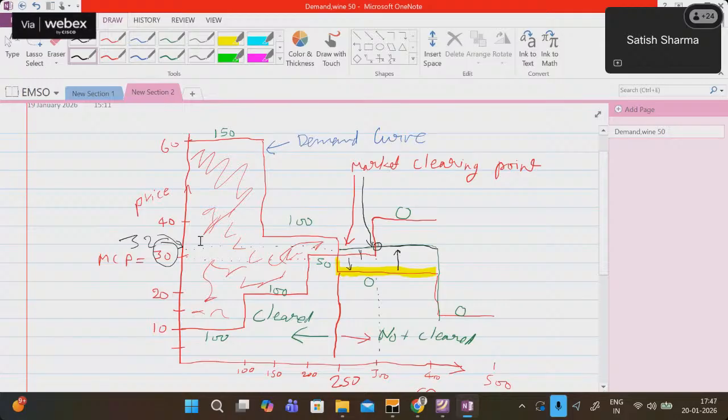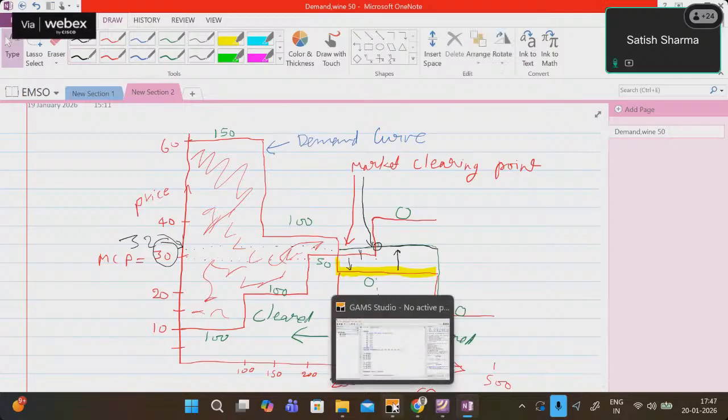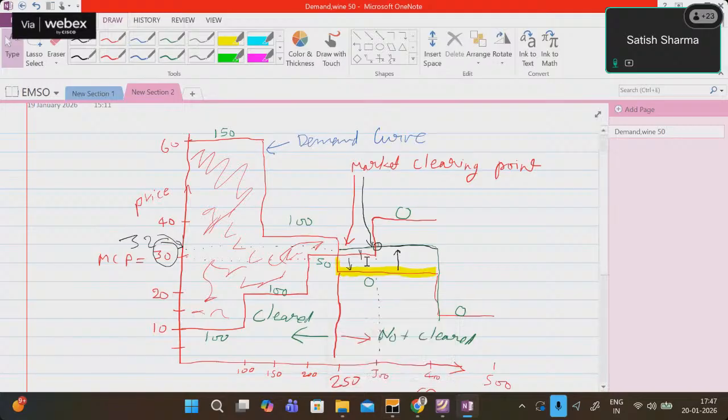Can we obtain the same results from the GAMS code as well? So if we shift there, generator 3, like with the modified one, P1 will be 100, P2 will be the same, 100, and P3 instead of 50, it will go up to 100, and D1, D2 are the same, 150, 100 demand, right?